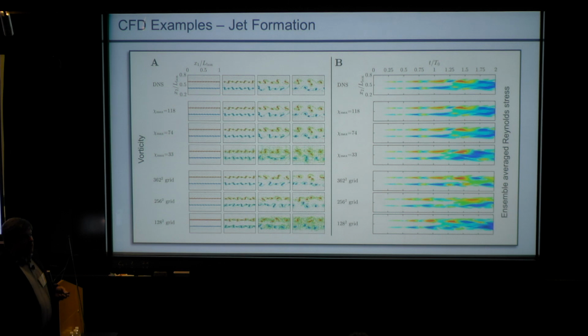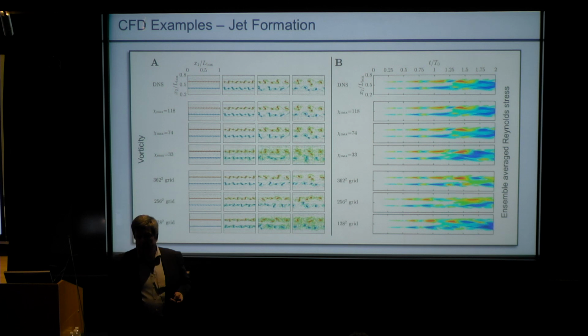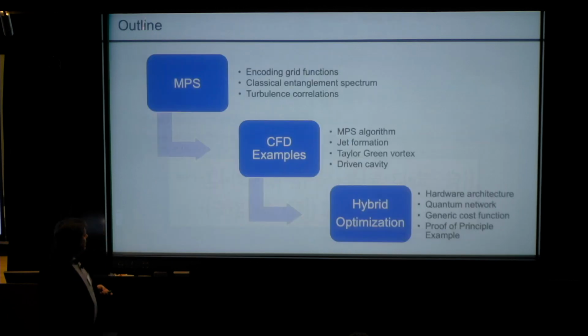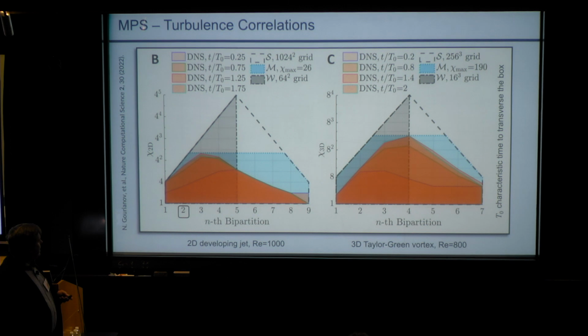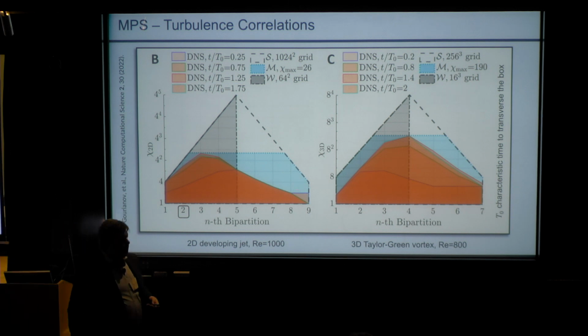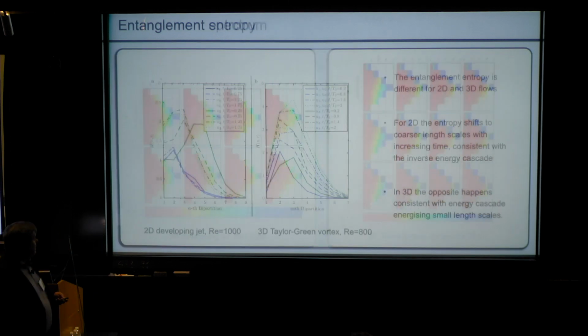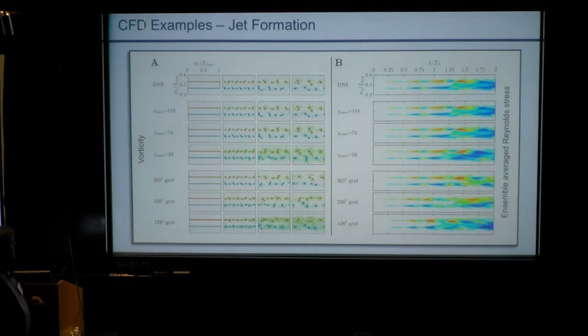Now in contrast, what we can do is of course the direct numerical simulation, but with an under-resolved grid, so-called URNDS. If you look at this plot, what that means is that instead of cutting my space of functions by cutting off the top of the pyramid, I cut the pyramid this way, okay? You can see the significant amount of function that I cut off that way. But this under-resolved DNS is something that people, of course, do because you can't have fine enough grids. It shouldn't be very good, as one can see from this initial plot, and that's indeed what we find.